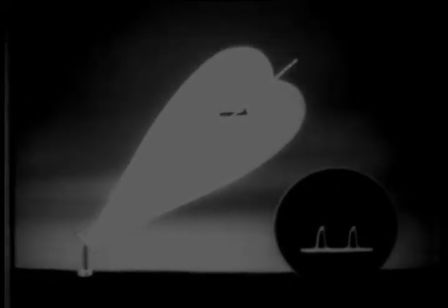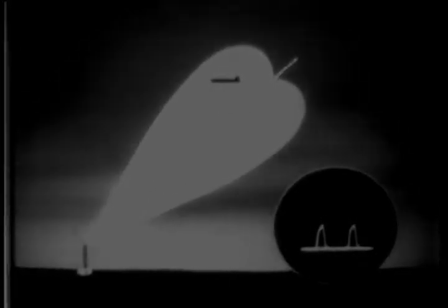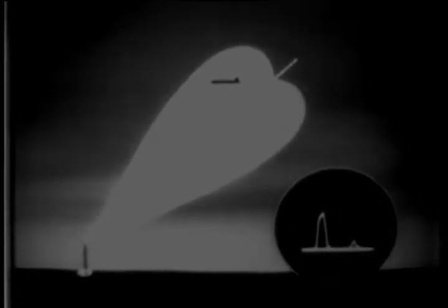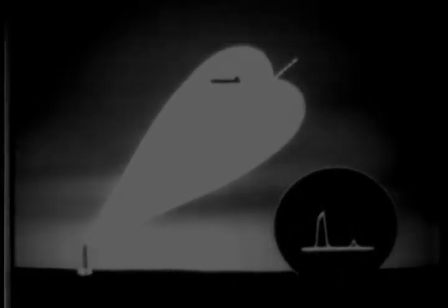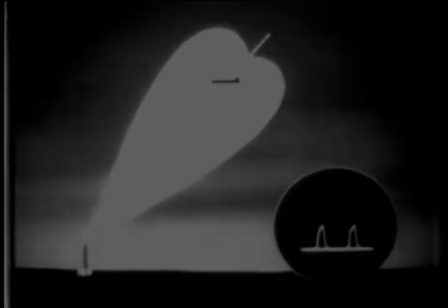Of course, the same idea holds true. Each lobe has its own pip and baseline. When the target's centered in the lobes, the pips on the elevation scope are balanced and your angular height data is correct. If the plane gains altitude, naturally it'll be in a stronger part of the upper lobe, a weaker part of the lower one. So one pip grows, the other shrinks. By turning your antenna toward the larger pip, elevating it in this case, you again balance the pips and get back on target in elevation.